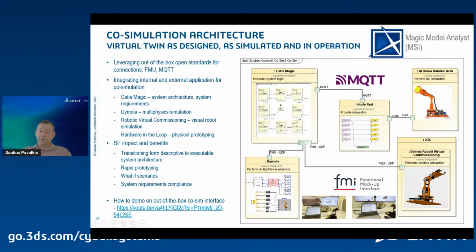So we are using that to control hardware. Then we are using the functional mockup interface generated from Dymola for interactive physics simulation in Dymola and with robotic simulation. This interface is parametric based, so it does not require tight integration and does not require the simulation to finish to do something. It is actually working live, interchanging properties and allowing you to have that feedback loop immediately.